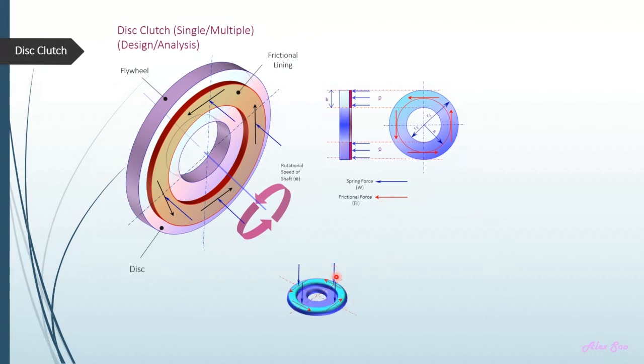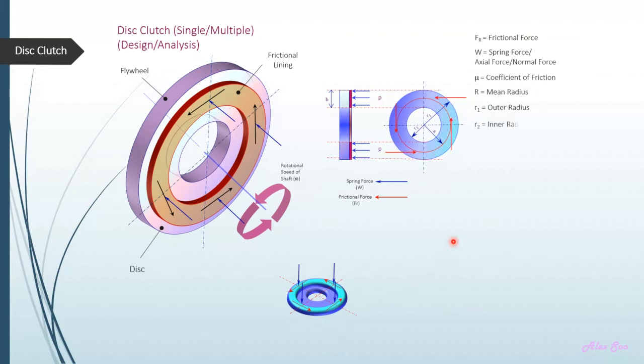So this is another diagram showing how the normal forces act on the rotating clutch plate and then produce these tangential forces here. Let me finish this. These are tangential forces and these are normal forces, and this is how they act. Because of these normal forces, you have this frictional force. That's how it operates, and this frictional force actually helps to grip the pressure plate and the flywheel all together.